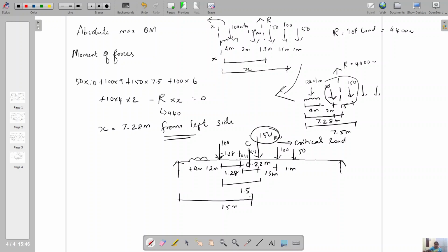Actually, this figure is slightly confusing. Okay, next page we will present it clearly. This is the center point, so this total distance should be equal to 15. So you deduct to get the edge distances, because our calculation needs the edge distance value multiplying for the bending moment value. So I am going to calculate this distance as 15 minus this 0.11, 0.11 and this 1.28.